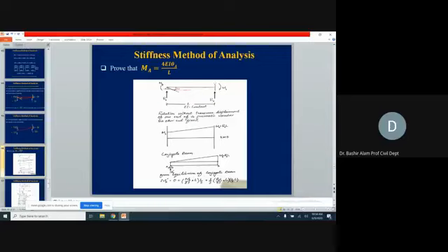So MA is drawn. The moment at B will actually be MA plus RA times L. This will be the bending moment because of these MA and RA values. So here we show MA plus RA times L. This is the bending moment diagram for this corresponding figure.